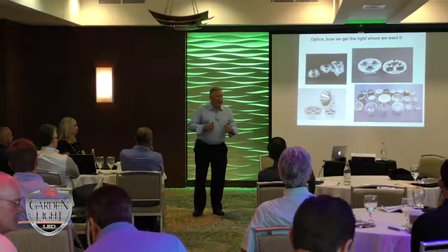In area lighting, we use sheets of LED optics that come on one big panel and cover 40 or 60 LEDs at one time. They get very close to the LED, which allows you to control it very well. But you can't do that with a large LED plane because the LED has such a large surface area. The most you can hope for out of it is low glare and to bend the light a little bit.